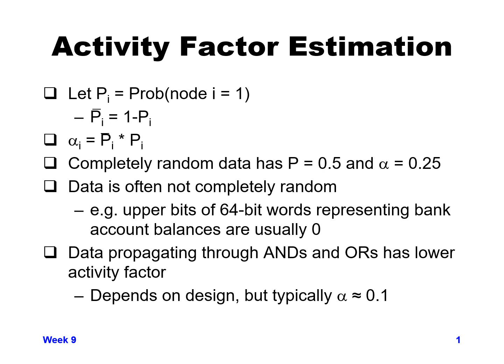And since you're trying to make a 0 to 1 and then 1 to 0 transition, the full transition from 0 to 1 back to 0 takes on average 4 cycles to happen. And so therefore for completely random data, you have an activity factor of 0.25 as your average.